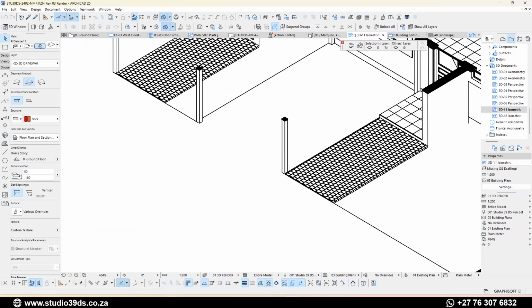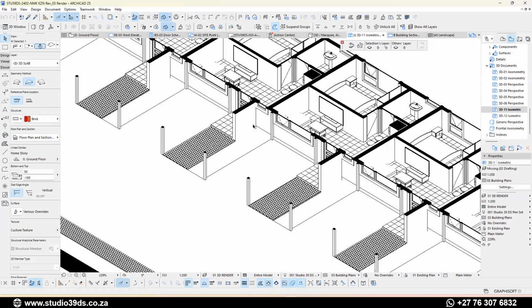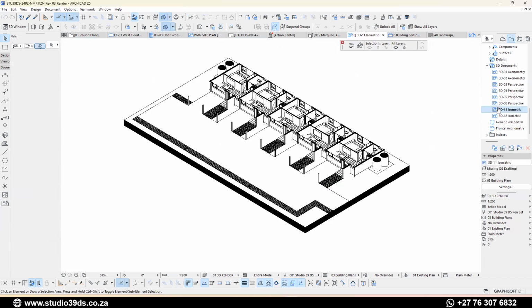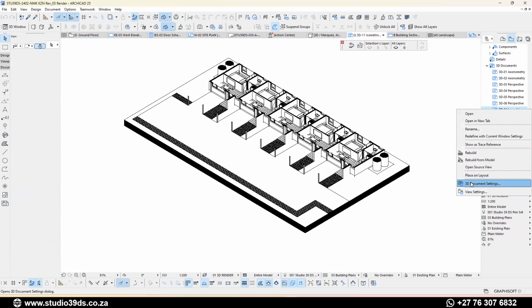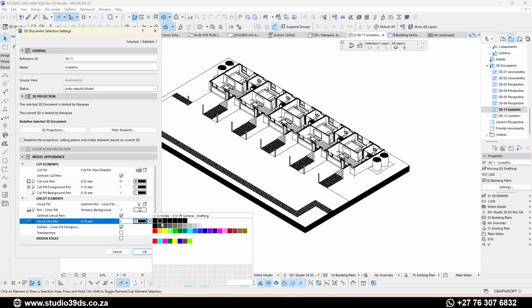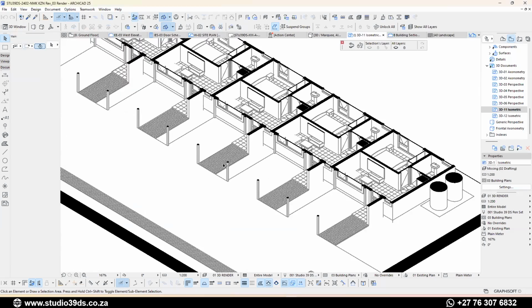And now the road is just shown in one color, and the sidewalks are paved in a specific type of paving. So I think this kind of works. I think I'm okay with this. I would like the pens of the fills to be a bit lighter. So the uncut pen, yeah, I think that makes more sense right now. Everything is lighter.